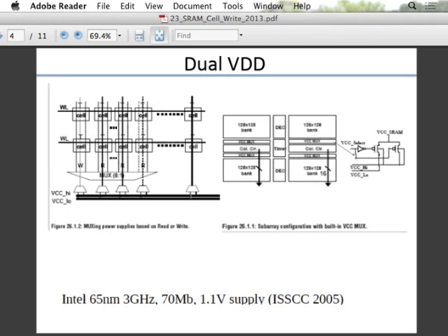Now, there is a notion of resistance of these muxes, right? Because this mux introduces a resistance and there is a certain maximum resistance you should allow, because there is always some leakage current. Let us say you are in the hold state and you have put VCC high. There is some leakage current, and that leakage current will flow from VCC high through the mux into the cell, and there are so many cells. So leakage of one cell times n cells in the column is the leakage current, and that will lead to a drop in the mux transistor here. That means the effective voltage to the cell will be less than VCC high by that drop. You don't want the drop to be too large because then the cell voltage becomes less during hold. For hold and read, if you recall, you want a high cell voltage for good noise margin, whereas for write you want a low cell voltage. So that means there is a certain minimum size you want to have for the mux.